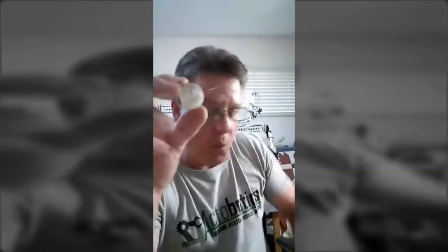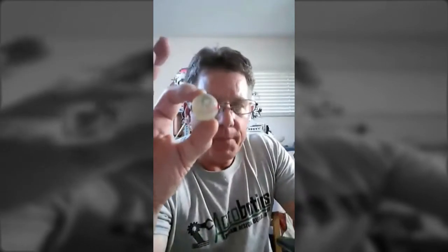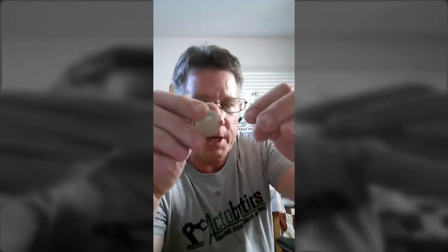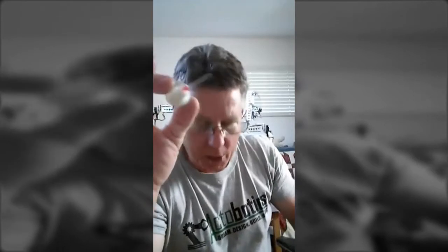If you've never wired up an LED, usually if you're wiring these up to 5 volt, 12 volt, and you wire an LED directly to that, you will blow the LED. It can't handle that much power. So you usually have to put a resistor in line, and what size resistor depends on what you're using for a power source, but usually you have to put one in line.